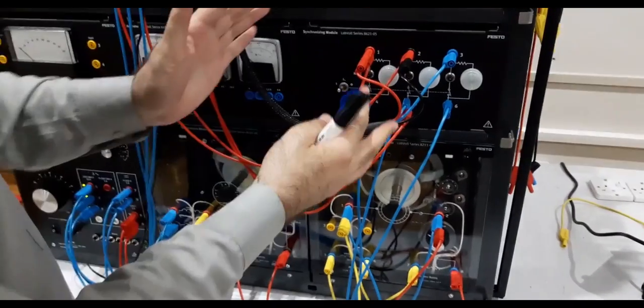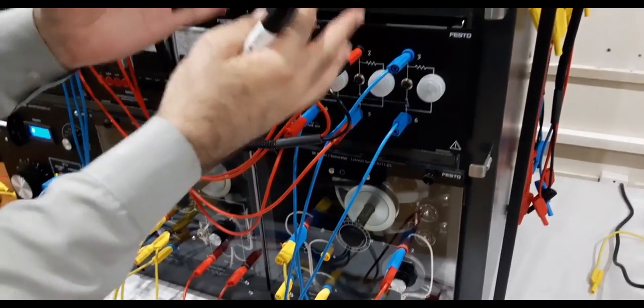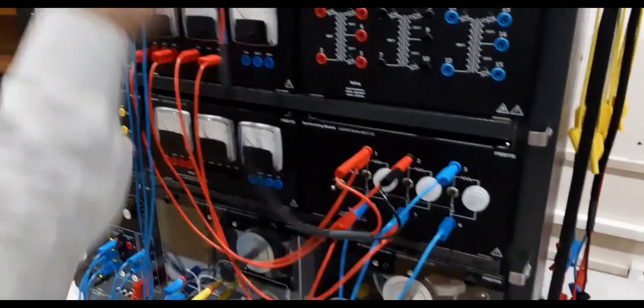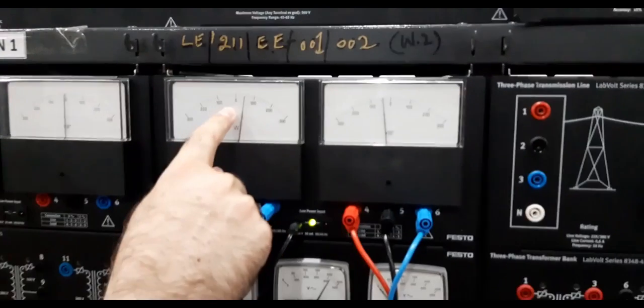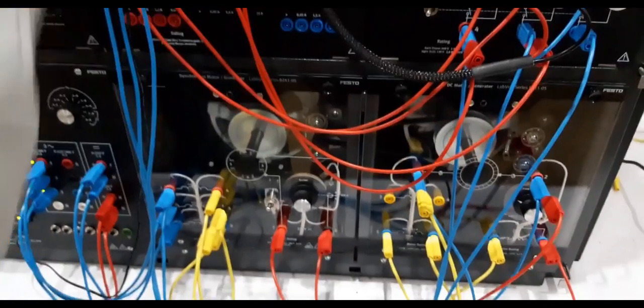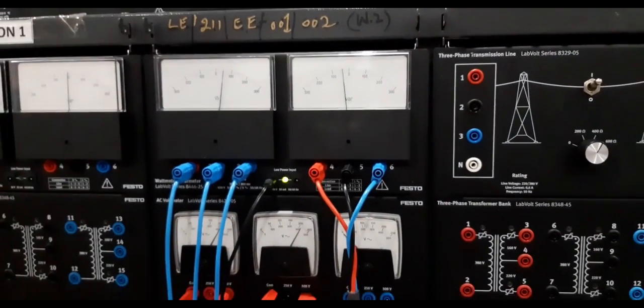What the system says to the generator is: keep yourself with us, we will provide power to you. So now the system provides power to the generator, and one can see the direction of the active power here. It is now negative. This synchronous generator is now consuming active power. If it starts consuming active power, it is no more a generator. What is now the nature of this machine?